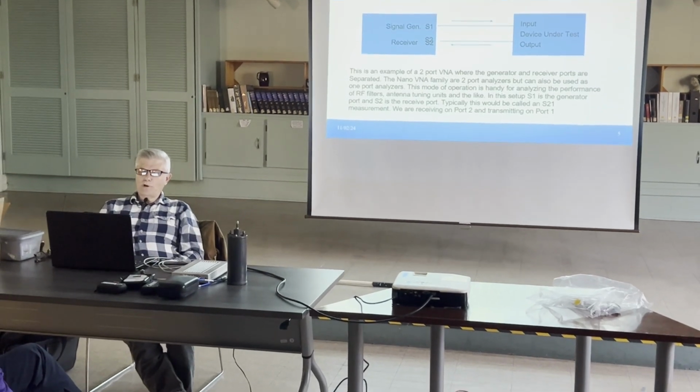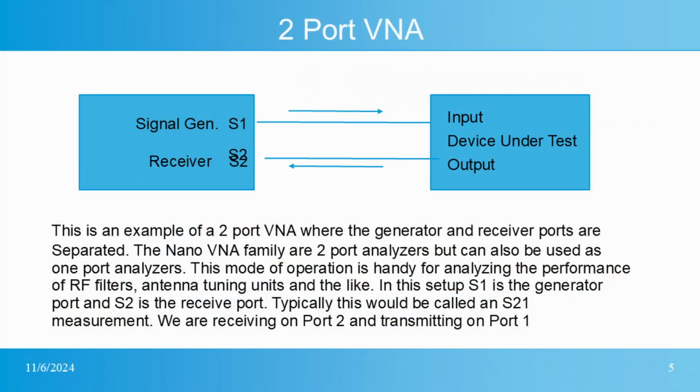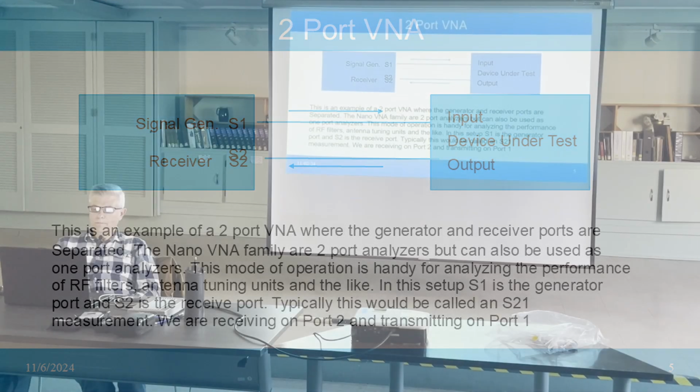All right, so this is a 2-port setup. I guess my graphic got a little screwed up on that, but S1 would be the signal departing the generator, going to the device under test, and then coming back on S2. So this is a 2-port measurement.